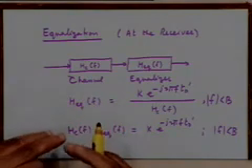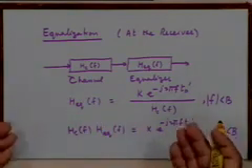And if you implement that, you can do that. But you are also going to amplify the corresponding noise components there. So you may undo the effect of distortion, but you may be enhancing the effect of noise, which may not be desirable. So in theory this is all fine, but in practice one has to work out a solution which takes care of these concerns. We will not go into further details at this moment. This is a subject which is properly dealt with in a course in digital communication.